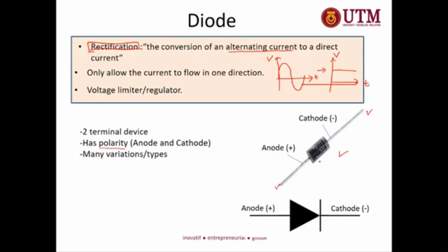Okay, so this is the actual look of the diode. And this is the symbol of the diode. The diode has the anode and cathode. See here, this line actually represents the line in the actual diode. And you see this triangular shape. The triangular shape refers to the flow of the current, positive to negative. So this is anode and cathode. When you see the symbol and when you have the actual diode with you, first you find this stripe or this line. This line is the cathode.